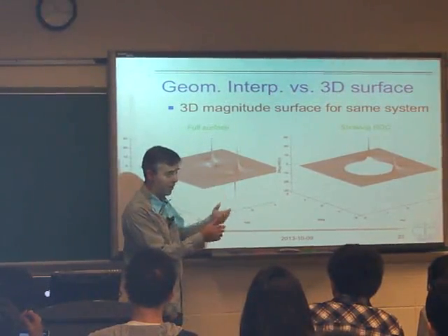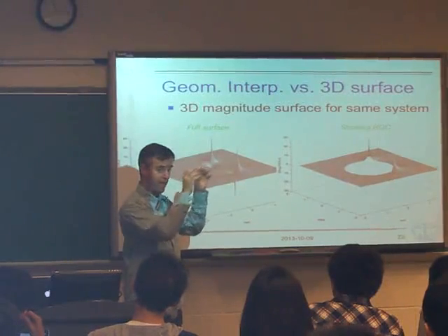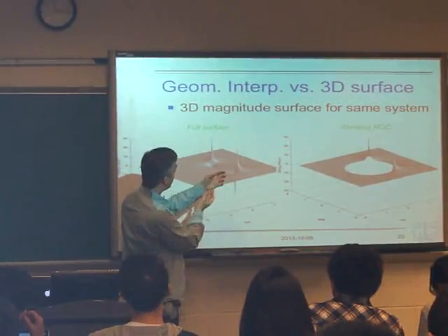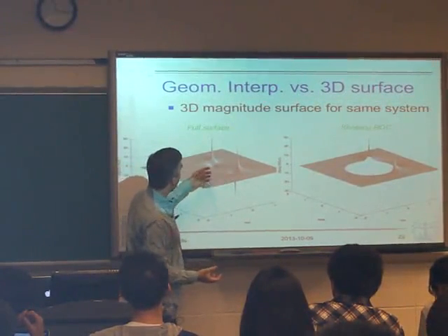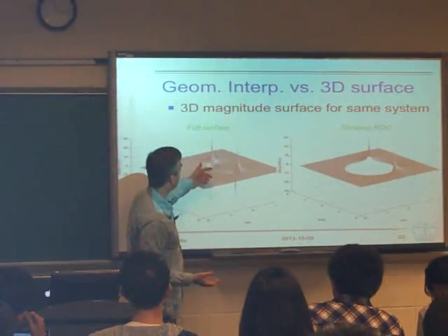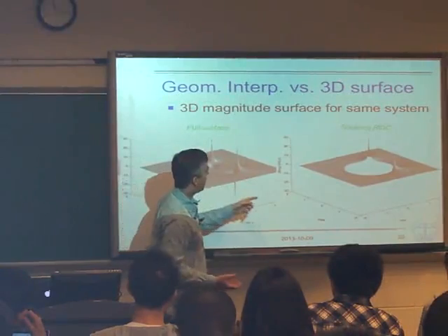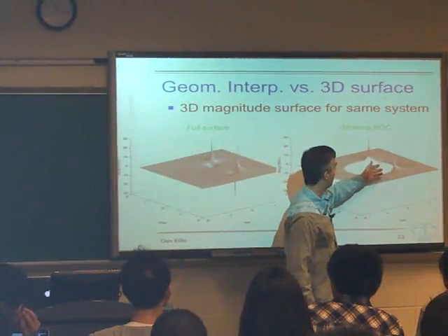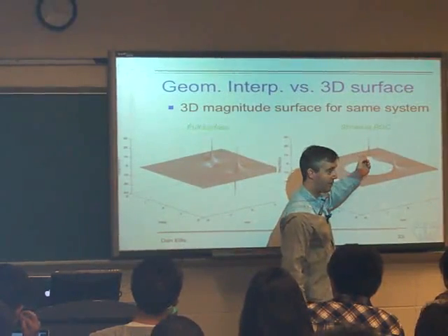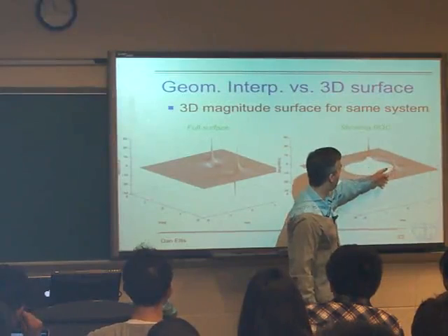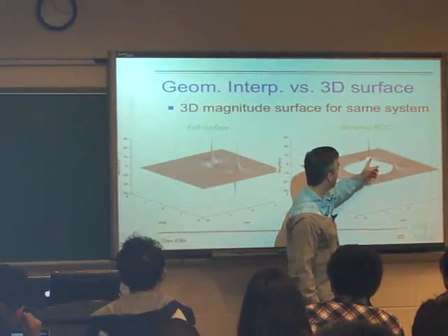That would be the same as saying we had the same factors in the numerator and denominator. They would just cancel out in the Z transform. But we've moved them apart slightly, and we've moved the poles, the sticking-up parts, a little closer to the unit circle than the zeros. So the overall effect, this is the actual magnitude of the Z transform, which of course goes unstable once we get to a radius smaller than the poles, but shoots up close to these poles.